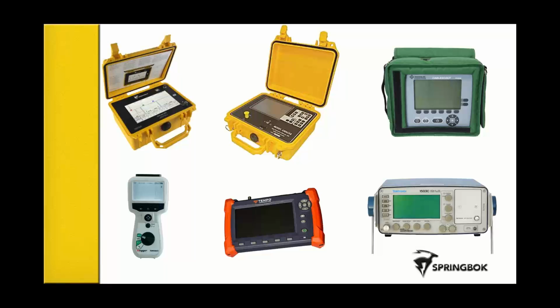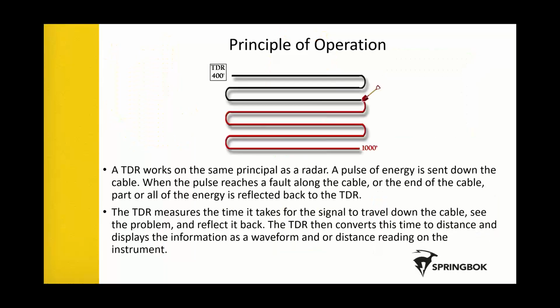So speaking of being called a cable radar, I like to use the analogy of a police radar gun, where you're going to connect your TDR to your cable under test. It generates a high frequency signal. It sends that signal down the cable. As soon as it finds an event, it reflects some or all of that energy back to the instrument. It takes the time that it took to get there and converts it to a distance: time domain reflectometer.